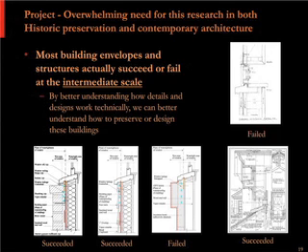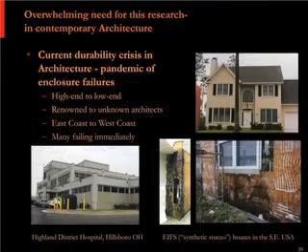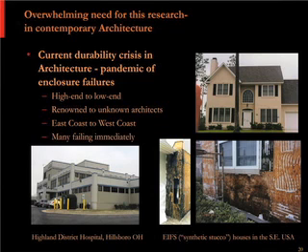So that is the scale of a window, the scale of how a roof meets a wall, the scale of a scupper, the scale of a bracket. Very little happening at that level. And in my experience investigating failures, that's really where it all happens. That's the scale at which buildings live or die in terms of their durability, is their detailing at that intermediate level. So these are all windows.